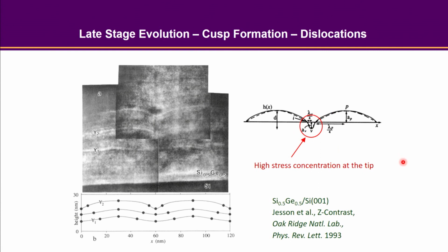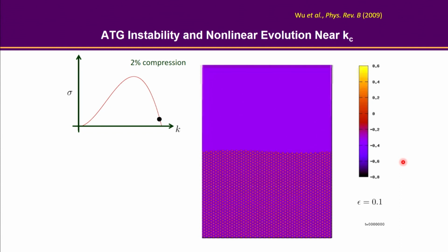Okay, so we have done some analysis, but today I'm going mainly to show you what the PFC simulation looks like and what parameters we use for this PFC simulation, all right? So you can set up a 2D hexagonal lattice, and first you set up a stress-free solid-liquid coexistent system, right? And once you have set up that system, now you just say the system dimension in the x direction is reduced by 2%. That roughly corresponds to a 2% compression of your system.